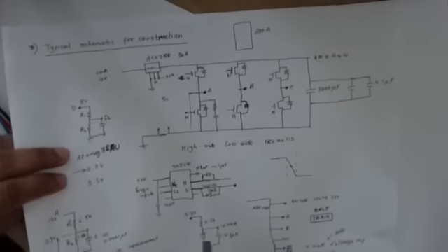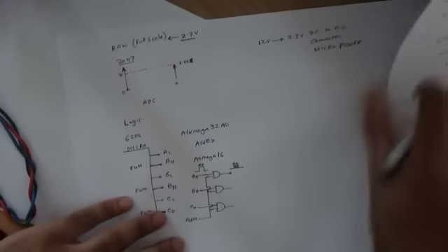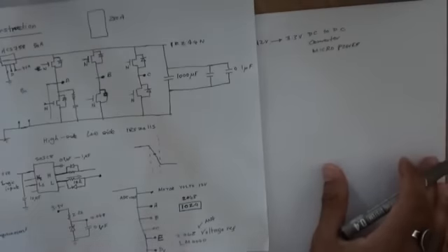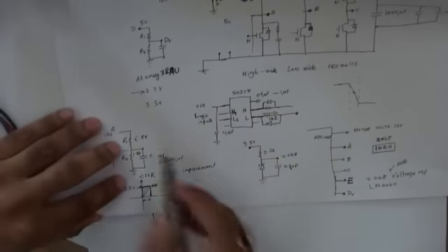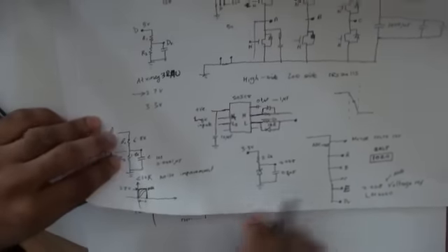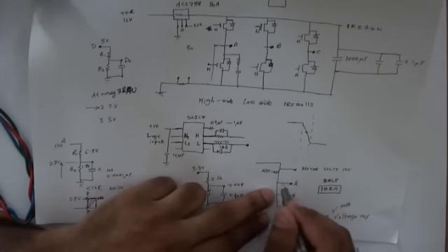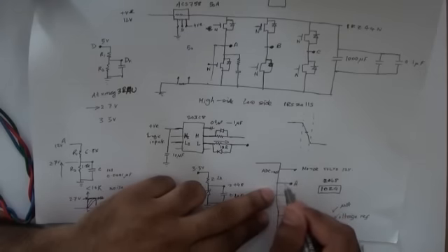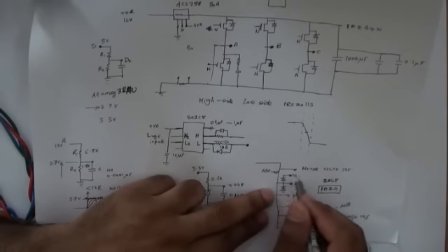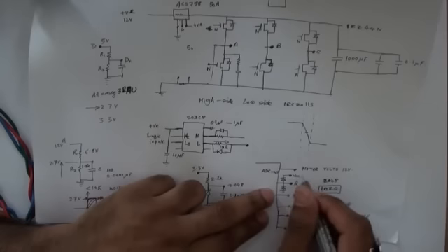So by having a diode clamp, if you look at going back to this level here, which is the bit that goes into the ADC part of your microcontroller, you want to have a diode clamp for each of the ADC inputs. So let's say for this phase you want to have a diode as such. This goes to ground, and another diode here which goes to your VCC. Now this VCC would have to be the supply of your microcontroller.